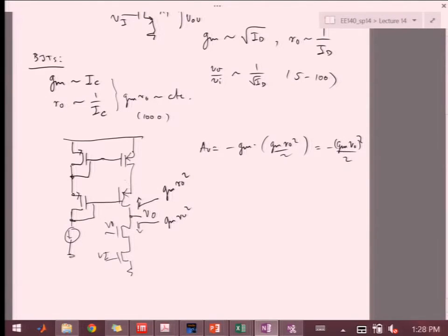And then with cascodes, if we do this one over here, it is not going to give us the smallest overhead because it's not a such cascode, right? So we're going to have to pay a threshold penalty. But at the bottom, if you adjust the VB, we could get away with 2 VOV, right? So if I change the current mirror topology, I can get by having something that's 2 VOV from the rail and then another 2 VOV from the bottom. So that will be my useful swing.